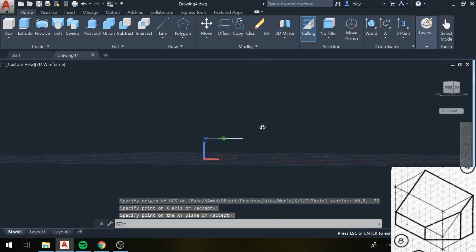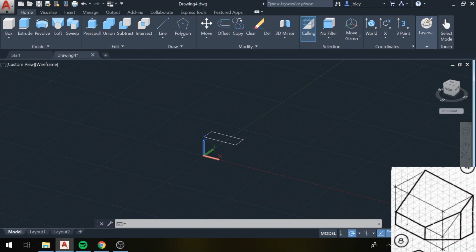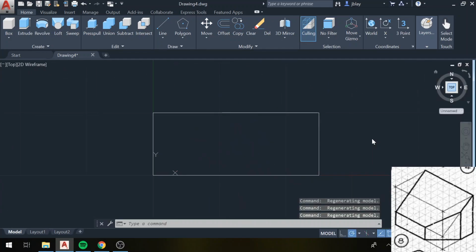And then I'm just going to do a quick rotation and make sure that my new plane is parallel to the rectangle I've drawn. If it comes out weird, don't worry about it. Just click down here and go back to WCS and start over, and you will be good to go. But I placed this correctly, so I'm now going to start my second sketch.